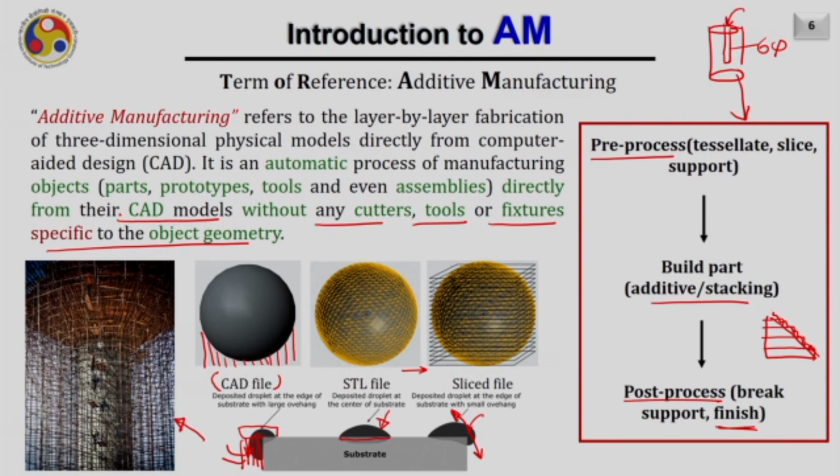Now, if there is a change in the geometry of the object, instead of a cylindrical object, I now have a cuboid object like this, and it has a hole of maybe 8 mm diameter now. In that case, first of all, your fixture will also change because you may prefer the 4-jaw chuck, and the drill bit may also change because now you may prefer to use an 8 mm diameter drill bit.